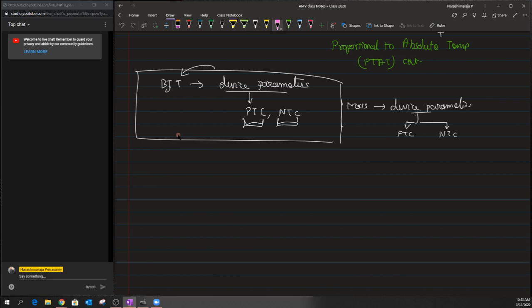So let me begin with this negative temperature coefficient voltage that could be generated from the BJT or a forward biased PN junction. Let me take an NPN transistor, and when you have this forward biased base emitter junction, then this results in a current flow through this BJT. Let me also assume that the factor beta is equal to 0, which means that the current IB is equal to 0, and we have a situation where the collector current is exactly equal to our emitter current.